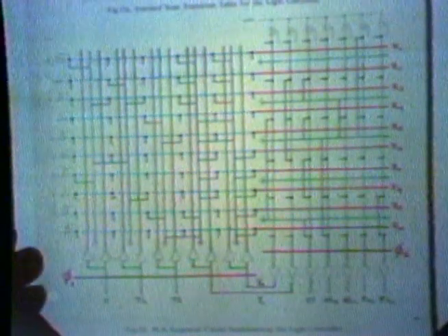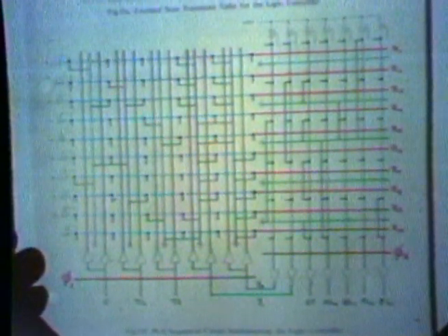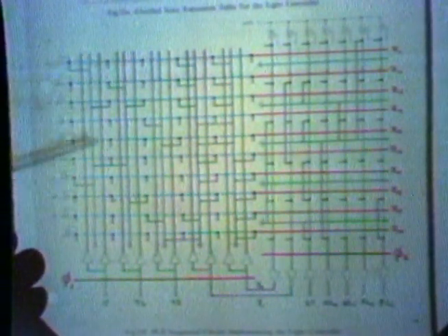I showed you before a PLA motivated by the combinatorial logic in a finite state machine. I don't want to get into too much of the details of how to design a traffic light controller, but that's what this is. It's a simple example of a machine that has 4 states. The 4 states are implemented by taking 2 of the output bits of the PLA.